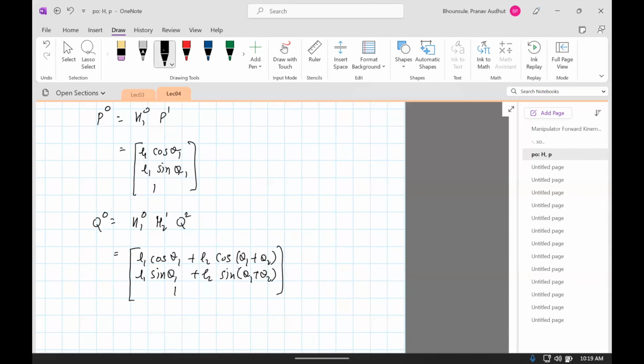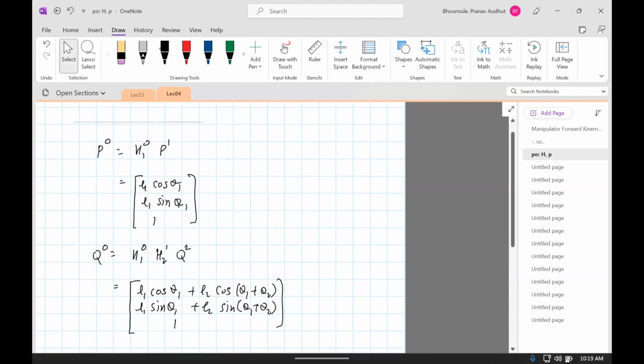Essentially we got the same thing as what we got with trig. And the good thing is that this can be automated to the extent that if you know positions of Q and P locally, then you can figure out the coordinates in global frame 0 by just using those formulas.